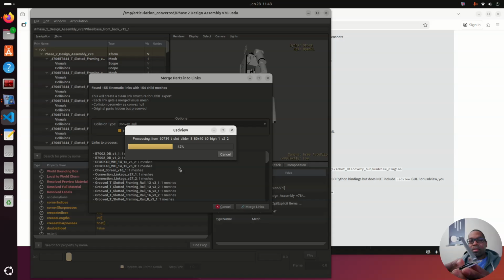I would probably do that because it would just make this thing much simpler. But the reality is, if this thing could move around, there is a possibility that these little tiny pieces sticking out here could become collisions, and you won't see that if you've simplified the robot down to a very, very simple structure. You're going to lose some of those features. The other thing you're going to lose is the masses associated with it.